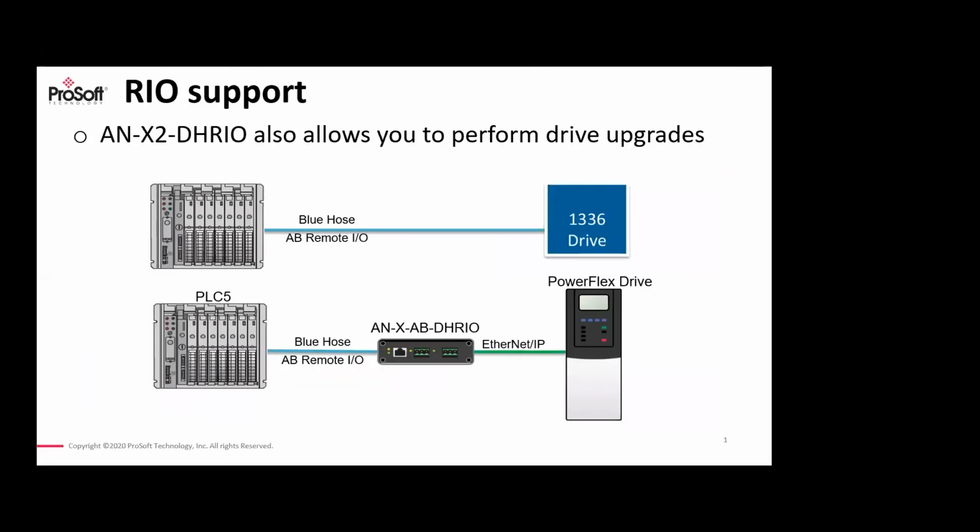You could have the ANX2 doing the same function for a legacy PLC with a newly installed PowerFlex drive, for example, and the PowerFlex drive would support EtherNet/IP, of course. And with our ANX2 gateway, you can have multiple drives working off the same ANX2 module. In fact, you can have as many as 4 drives connecting to one PLC through a single ANX2 module. So the iterations for remote I/O migration are many. The ANX2 can handle most, if not all of them.